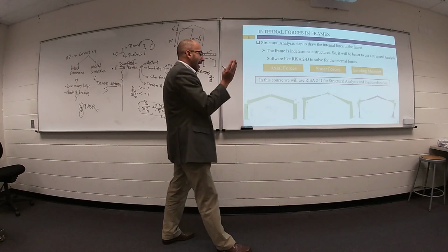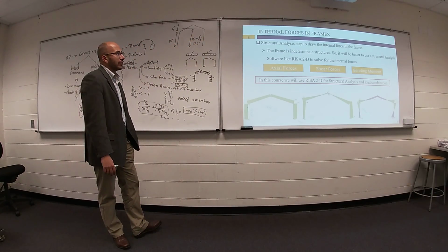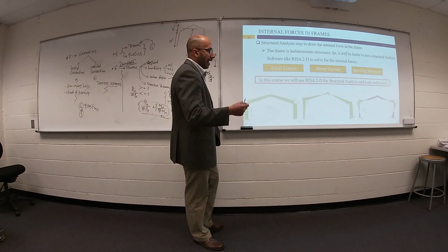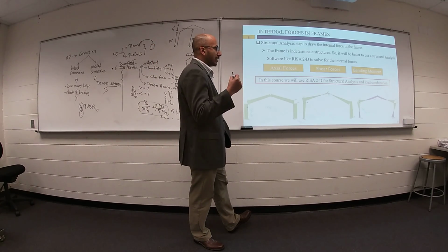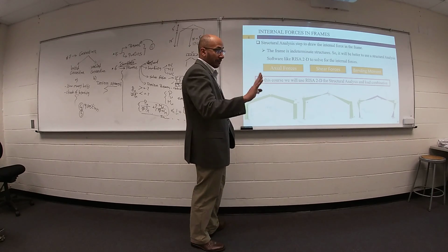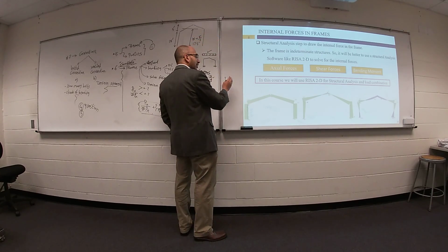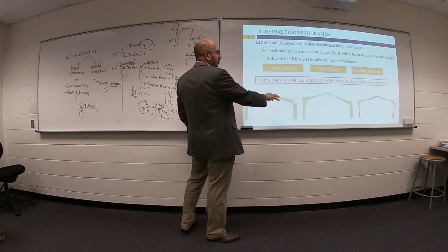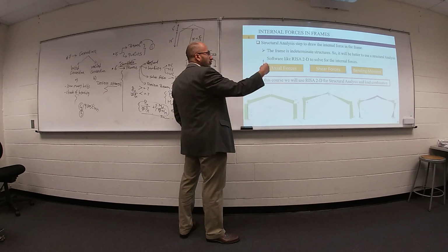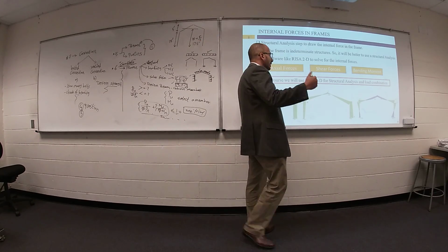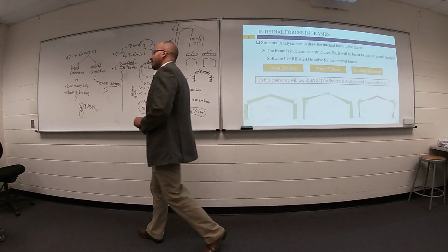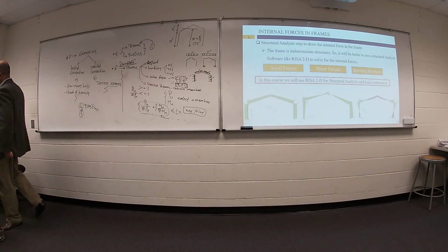So we have P ultimate and M ultimate. Go ahead and select a cross section, a W shape, and do your calculation to say whether your selected cross section is safe or not safe. If your cross section is safe, say it's safe and economic. Or it's safe or more safe, not economic. Or unsafe, I need to increase the cross section. Just only one trial, but let me know what you think: safe, more safe, or unsafe?